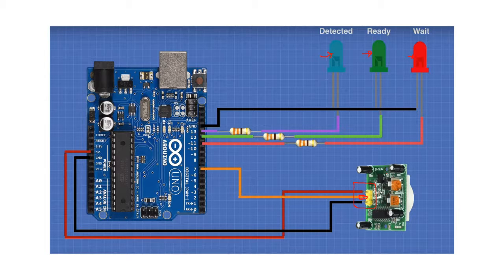Then the next would just be, again, as Mwalimu Maxwell has just noted, about the coding. So the coding, again, becomes your part. And I want you to see the LED. Maybe we may be looking at the LED in the next level, because the LED has legs. There's a leg which is short, the other leg is usually long. The leg which is long is usually the positive, the one that has to receive, the one that's taken to put on the pins.